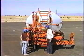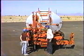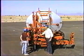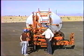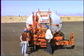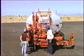When we're heating and circulating the tank, because we are heating, we're going to run the pump. We just run the pump at full speed on the pump control in the cab at a dead engine idle, just like the engine's running now. That runs the pump at about 200 gallons a minute, and that's plenty of circulation in the tank. It does a very good job as far as dissipating the heat.